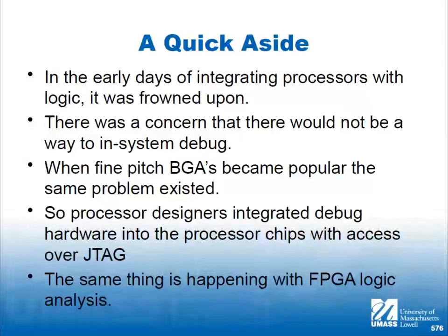So wouldn't you know, at the same time, the FPGA manufacturers needed a way to get the FPGA program into the FPGA. They used JTAG too. So eventually, maybe 5 years after this event, Xilinx came out with the Zynq processors. And actually before that, they had a different version. They had the Virtex-II Pro with the processors on it, and you controlled both the FPGA and the processor through the JTAG port. All the problems are solved.